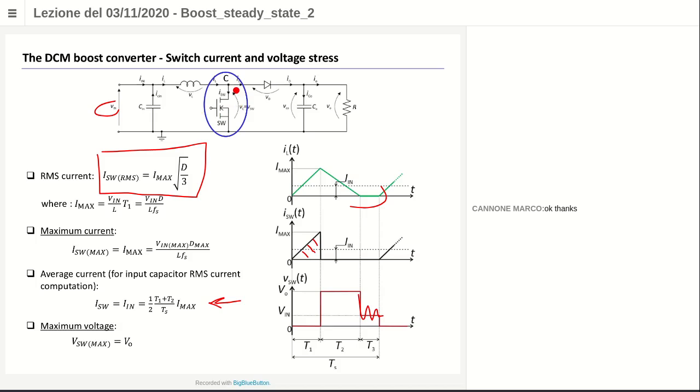The diode off is a large capacitance, and the MOSFET has its own output capacitance, and even the inductor has its capacitance across it, in real component practical circuits. This leads to an LC resonance circuit, where L is the proper L of the circuit, and C is the summation of all the parasitic capacitances you can have in the circuit. So this brings you oscillations.